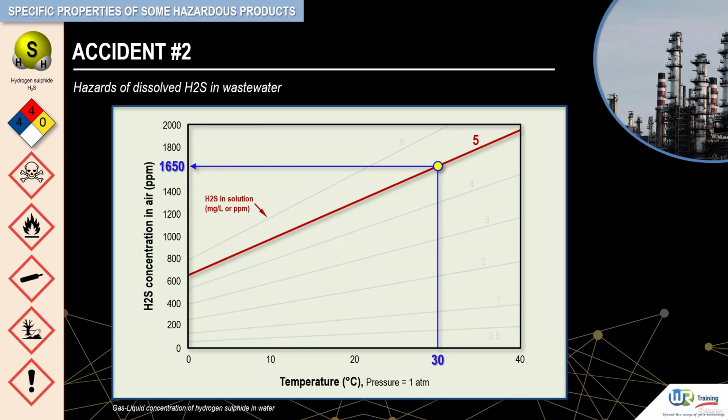This is way above the IDLH of 100 ppm. What it means is that under these conditions, the air around the vessel is not fit to breathe. Hydrogen sulfide has reached dangerous levels, turning the space into a toxic, deadly atmosphere.